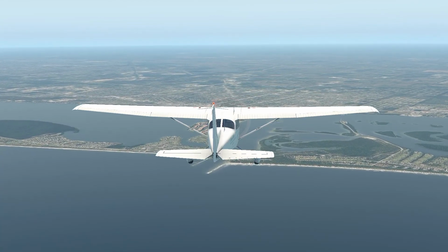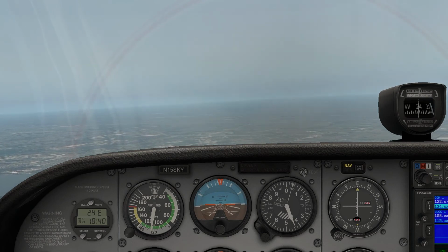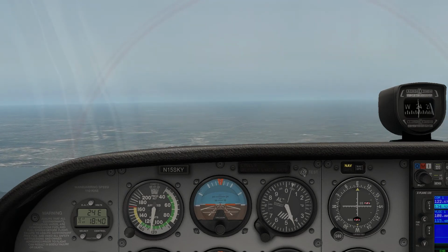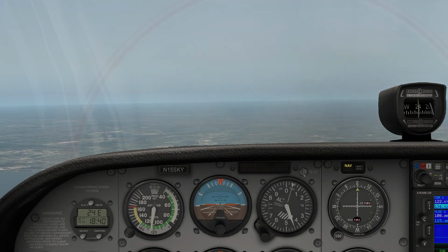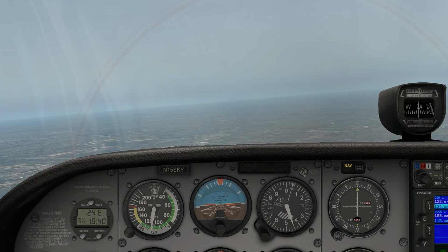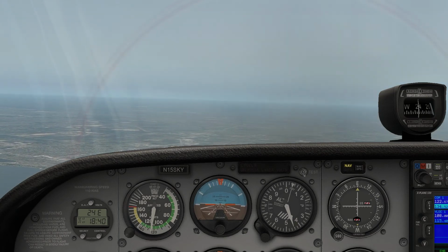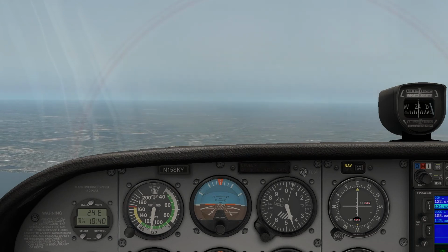To compensate for this, the sim pilot must pay special attention to those aspects that would otherwise be obvious from the sensations you would experience, like the airplane banking slightly, which would introduce a turn. This is by far the most common mistake a sim pilot makes, not paying attention to the airplane's banking tendencies. So for this reason, your first lesson is to learn how to identify when the plane is banking slightly, why it is doing so, and how to instantly correct it without overcorrecting.